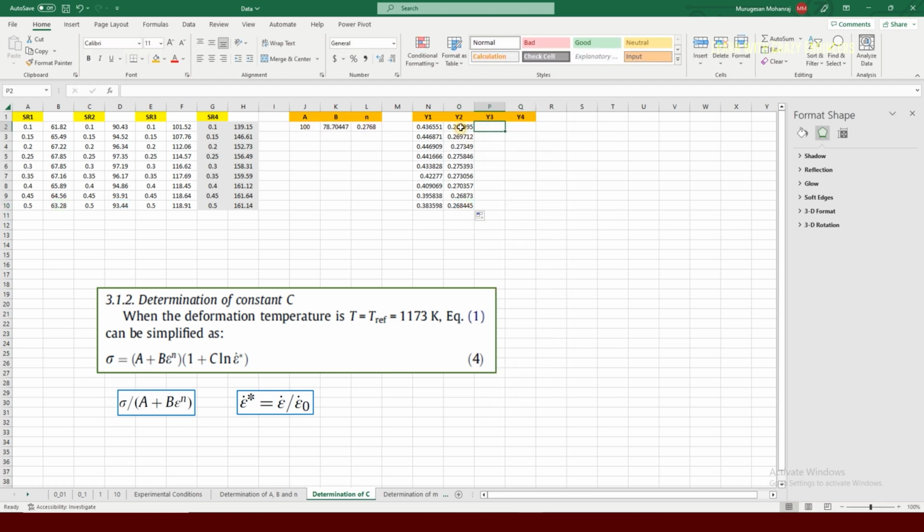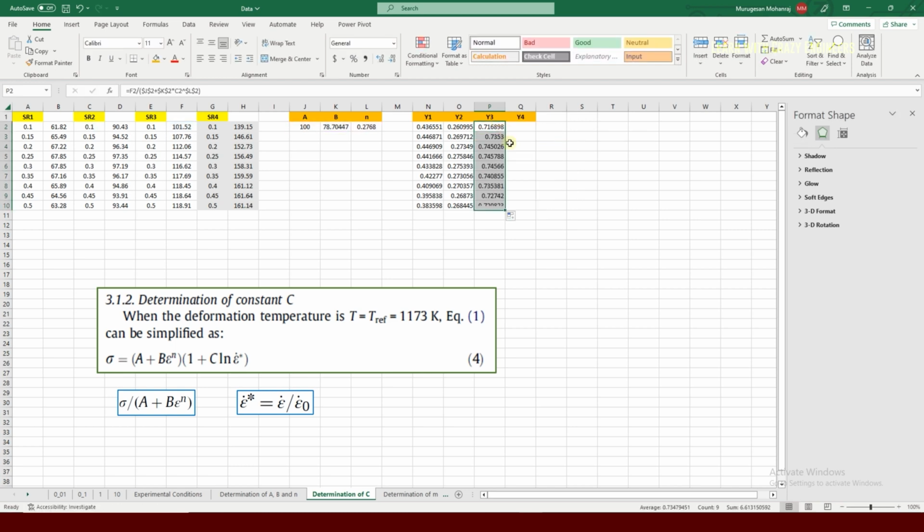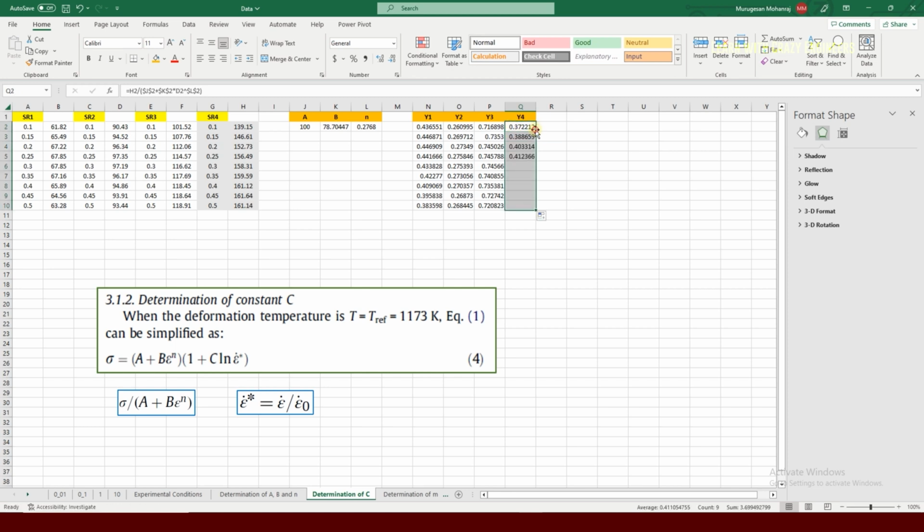And then do the same thing, just copy and paste it, and then change this to F, and then enter. Good. And then Control C, Control V, G, then change to H, which means I'm just choosing the stress rather than strain, because when you copy paste in Excel, it will just shift the column reference. That is why we are repeating and deleting the C column and changing to D, so that it will calculate only the strain. And then for strain, first we have to make this parenthesis, which is based on the reference strain and selective strain, which is nothing but just to consider dimensionless strain, just to say D strain.